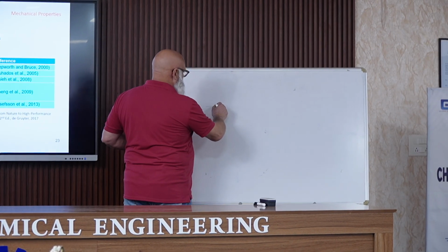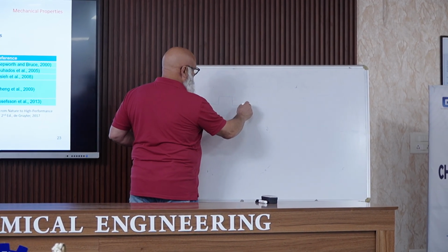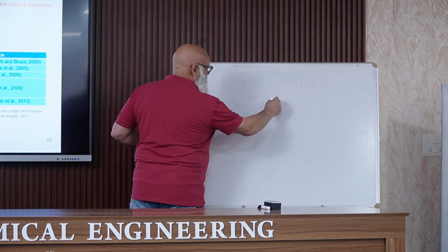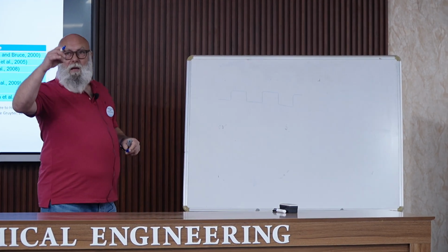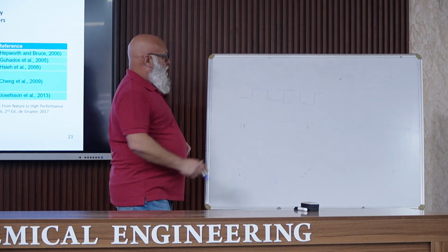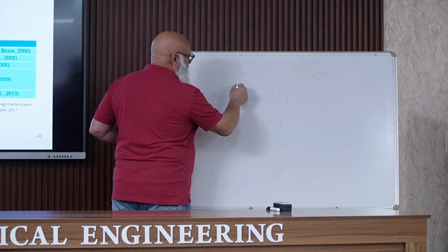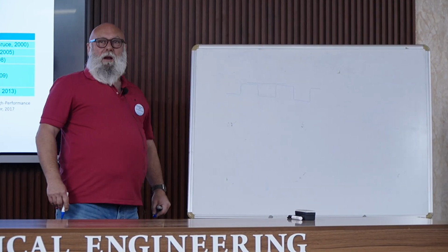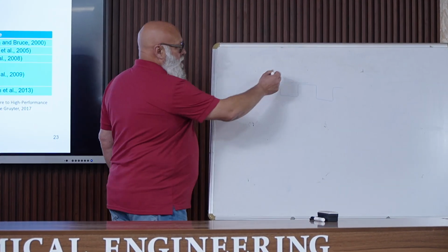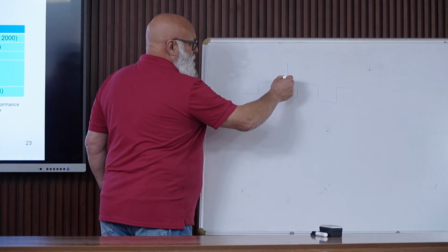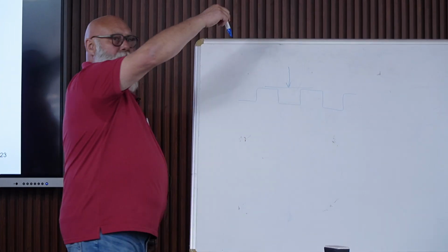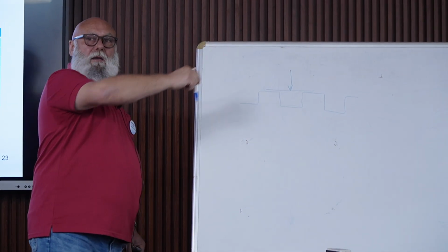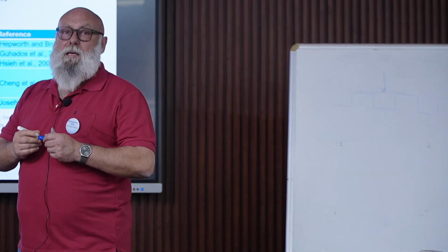We use a substrate with some grooves like this, and the nanofibrils are deposited on this surface, hoping that one nanofiber can be like this. Then with the AFM tip, it's possible to exert a force, like in a three-point bending test.